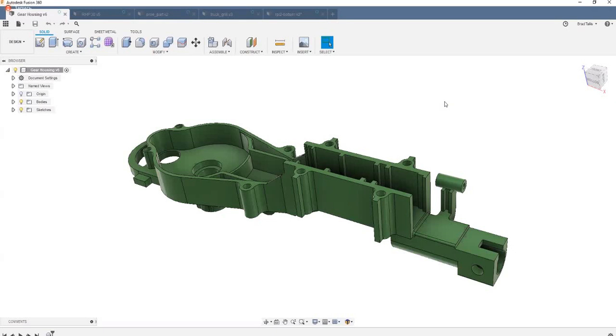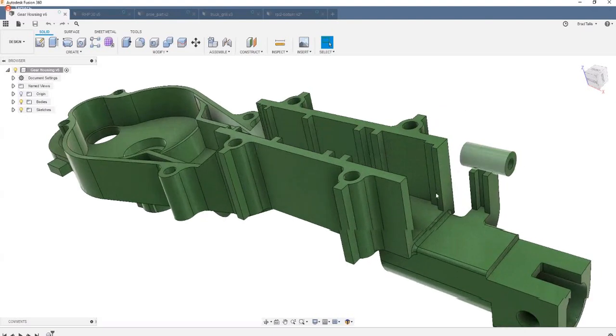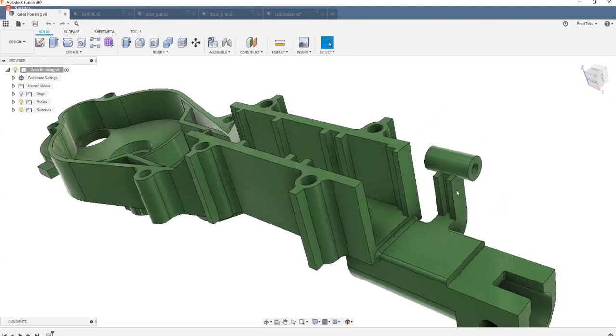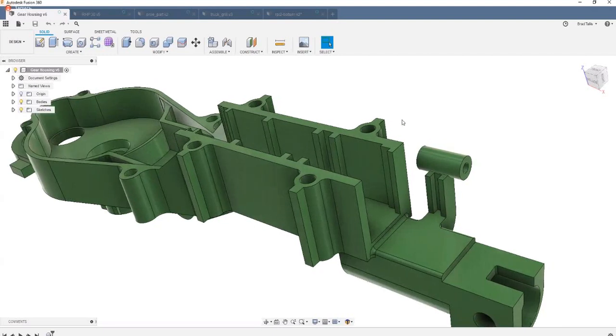We wrote our own direct modeler, called Solid Designer. There were no parametrics really in it. You worked directly on the model, which means if I wanted to move a feature, I would just say move that feature 10 millimeters. I didn't go into a sketch and change a dimension or anything like that.